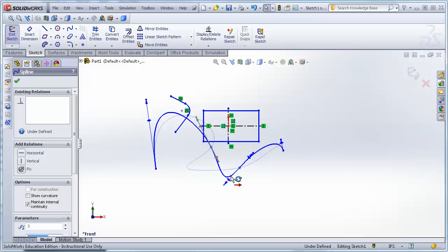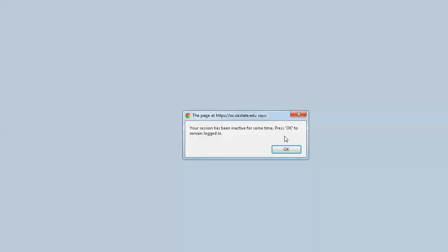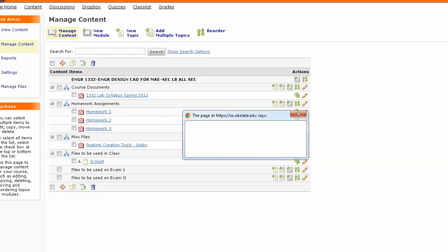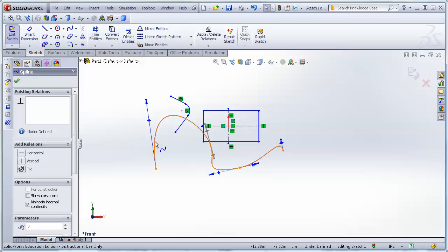Okay, and so these handles on the spline control, oops, I got an error message from another program. I don't want that at all. So let's get back to SolidWorks. So I've been playing with these handles. I can independently grab the direction handle for the spline, or what is called either the tension or the weight value, depending on terminology you've used. Some people like to call it tension, some people like to call it weight. Either one is probably fine. Each one can be independently controlled.